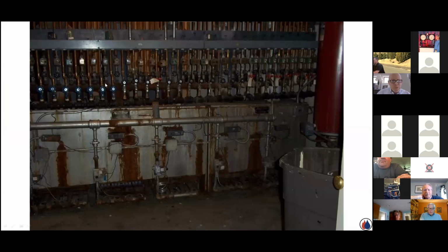But what I was looking at is this. You look at all of these zone valves. I didn't bother to count them, but there's got to be close to 20. And if you look at the size of the piping that's supporting all of these zones, it's way undersized relative to what it potentially needs if all of the zones were calling.